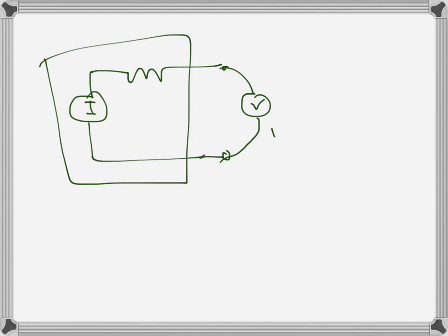That means we are in effect allowing a 10 mega ohms resistance path for current flow. This is not infinity, so a current can flow. So that is Rs and this is Vs, and the voltage measured here is 50 millivolt.